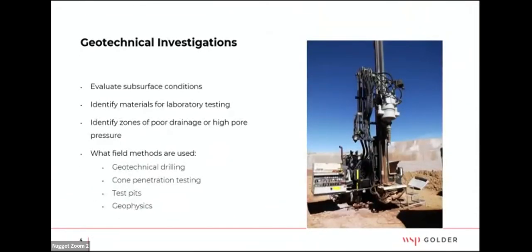So what are we looking for in geotechnical investigations? We really need to see what's going on in the subsurface. One of the issues on the design side is that if we're lucky, we might get a ton of ore that we use in our lab testing up front, and somehow we're supposed to extrapolate that to millions or hundreds of millions of tons of ore. We're never going to be able to do that. There's never been a sample that would be considered representative of that scale at what we can do in the design phase. So really your heap becomes the experiment.